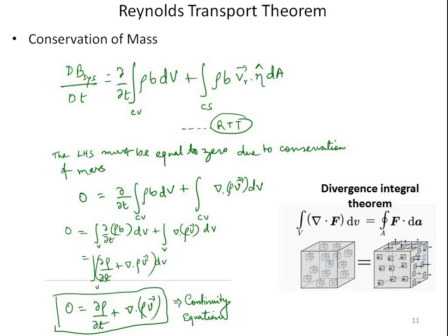These are actually design equations for chemical reactors and in every aspect of microfluid mechanics. So when conservation is happening, there is no generation and no consumption, and if the system is at steady state, there is no accumulation. In the LHS dV system by dt, there is no accumulation of the property, so we can write it as 0. By this definition, the LHS becomes 0. Now we are left with our RHS, which is our Eulerian term.